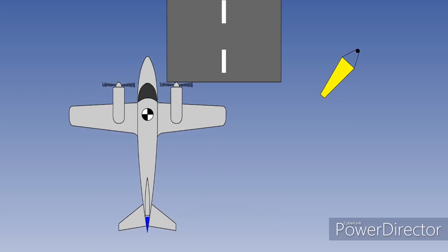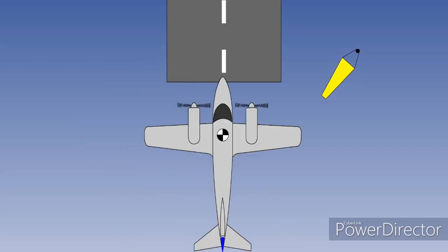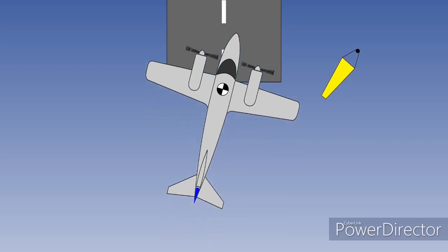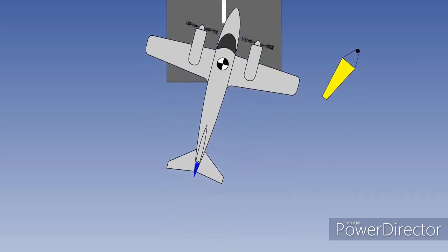What you should do is position the aircraft on the extended runway centerline, but fly it in a direction slightly towards that from which the crosswind is coming, in this case to the right. Please note, you are not using the rudder to do this. You are now tracking the extended runway centerline, but with the aircraft at an angle to the direction of flight. If you were to touch down in this attitude, you would damage the undercarriage.